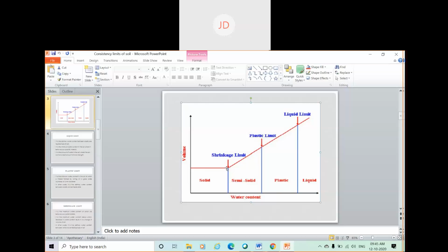We are talking about fine grained soil. Fine grained soil has a capability to increase its volume, because it has an ability to hold water, because it can attract water components, the hydrogen ion and hydroxyl ion, by the minerals present in a particular fine grained soil. So we'll not go into so much detail for now, but you just concentrate here. The fine grained soil, especially clay soil, has a capability to hold water, and for holding more water, it can expand its volume, actually by expanding its volume of voids. The volume of voids can be expanded.